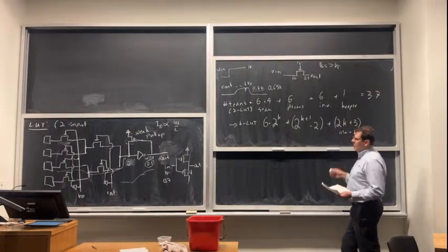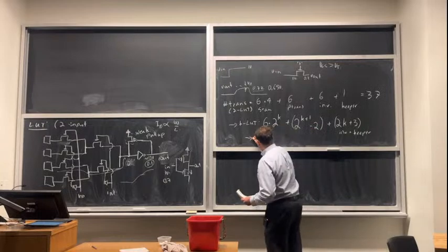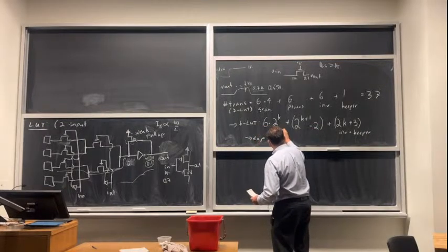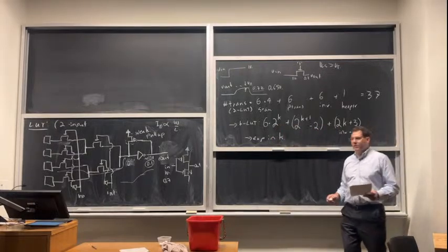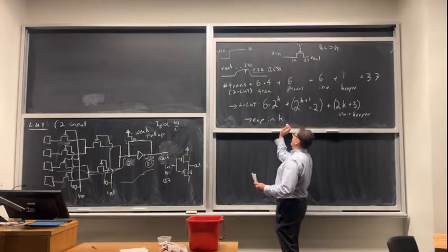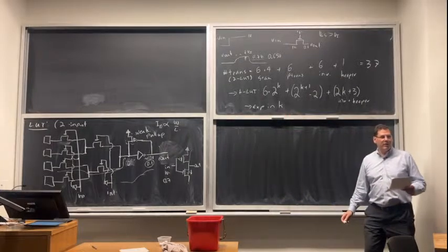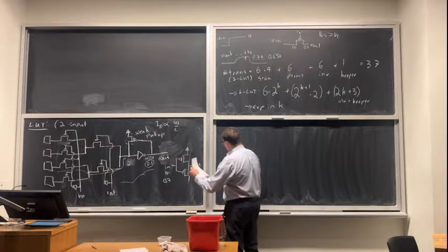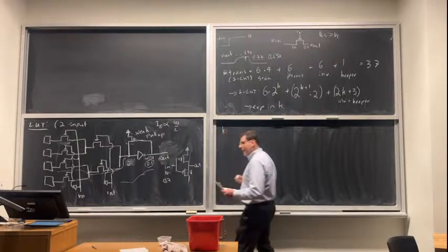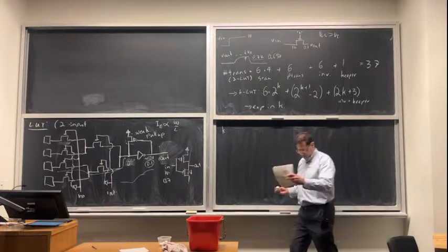Okay, and we see again it's exponential in K, which we saw before. We looked at, are any of these logic elements really scalable? And we said the LUTs grow exponentially. We can see that when we count the transistors. So that's kind of comforting. That's good. Okay, the last thing I want to do is, so we've gotten a transistor count, which is a not terrible area model, but we'd like to do a bit better.